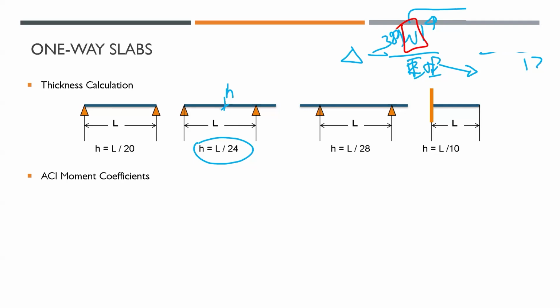And that creep factor is 2 to 3, 4 times the instantaneous deflection. So that means long-term deflection will be primarily controlled by the self-weight, which is already included in the thickness calculation. So this formula has backward calculated those things and come back from there. So you don't need to worry too much about that. Yes, of course, live load deflection will be there, but they're short-term and they recover mostly.